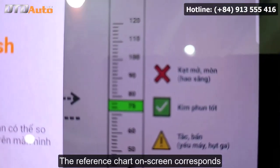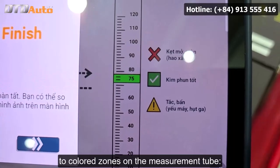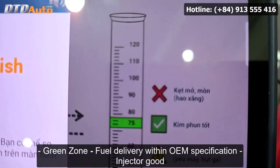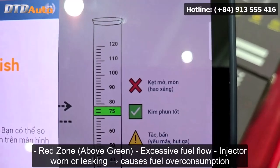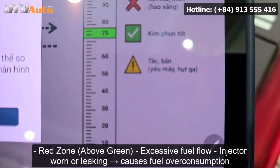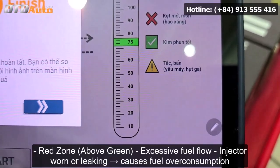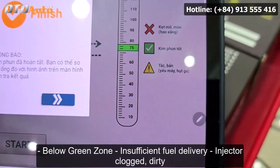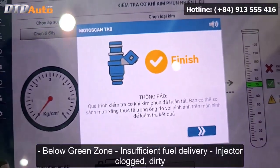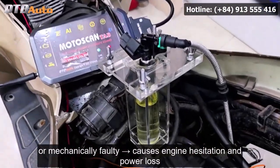The reference chart on screen corresponds to colored zones on the measurement tube. Green zone, fuel delivery within OEM specification. Injector good. Red zone, above green, excessive fuel flow. Injector worn or leaking, causes fuel overconsumption. Below green zone, insufficient fuel delivery. Injector clogged, dirty, or mechanically faulty, causes engine hesitation and power loss.